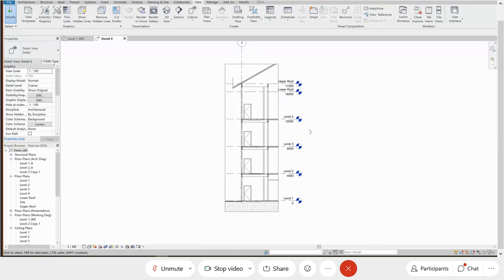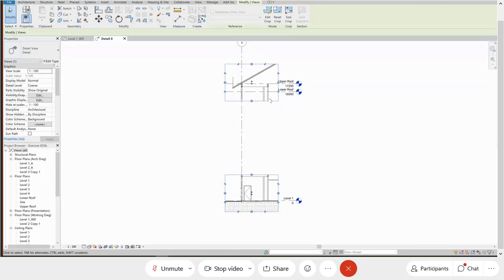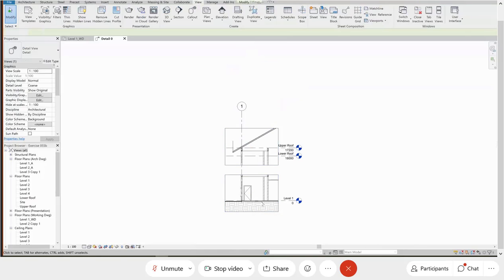What can you do? In Revit there's a very simple solution, which is this break. Okay, the break, which is very useful when you create your detail. It can be horizontal or vertical. Here you just click it and it breaks into two, then you can drag it.